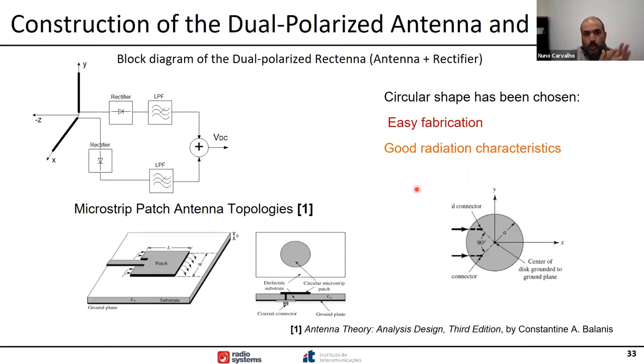Well, then you go through your beam and you receive your signal. What is the problem of receiving the signal? Well, first, you should guarantee that you have a precise alignment of your transmitter and your receiver. This is mainly for polarization. Well, you can use circular polarization, but you lose a little bit when you use circular polarization. So we try to use dual polarized antennas. Why? You can say, okay, but why not align the antennas on both sides?